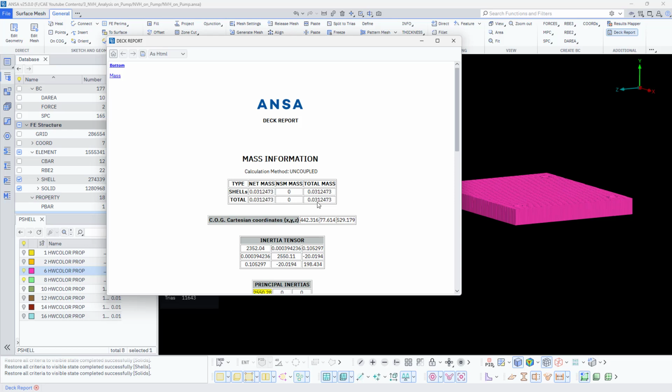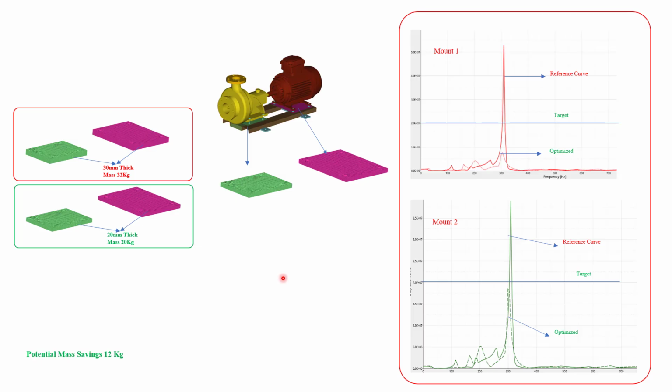Okay. Well, finally, to conclude, I'd like to take you through a few assumptions, and I would like to conclude with the validation here. So initially, the plates which you could see here, these two were weighing around 32 kgs, and the thickness was around 30 mm, correct? And then what I did is, for this analysis, I considered the least possible thickness of 5 mm for these plates.